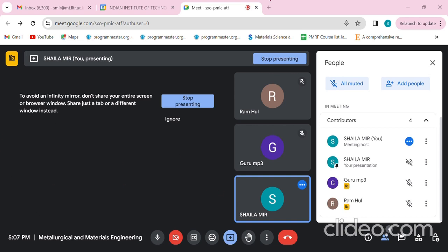Magnitude and direction. Okay, so right, the Burgers vector gives you knowledge about its magnitude and the direction of the dislocation line. You have seen it represented like this. For example, a by 2 is the magnitude, a under root of 2, and then you are also given a direction along which this Burgers vector is, say for example 110. So we have both magnitude and direction of a dislocation line given by a Burgers vector, which is represented by this B vector.